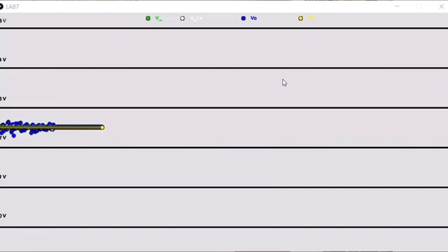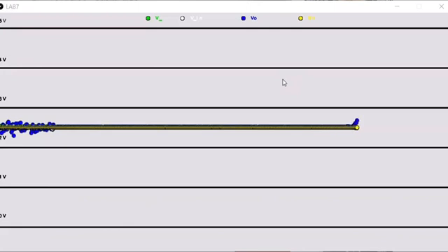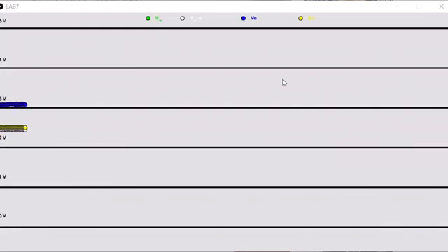Now taking a look at the processing graph. So I display 4 variables: V minus, Vin, Vout, and V plus. So I start from the virtual ground, which is 2.5, and I'm going to start moving very slowly. As you can see, as I start slowly moving my Vin, I see a greater change in a positive direction of my Vout. This is because this is an inverting amplifier.